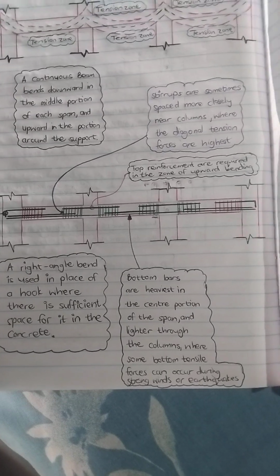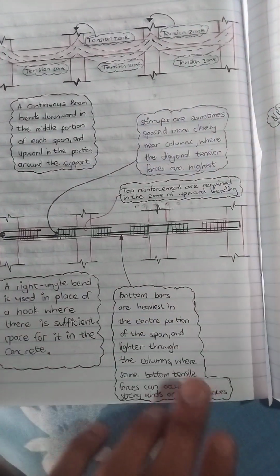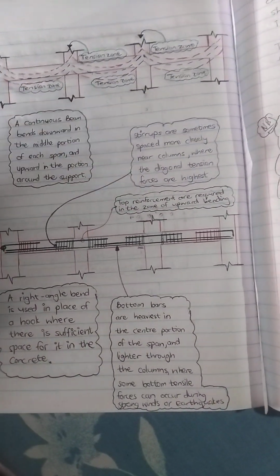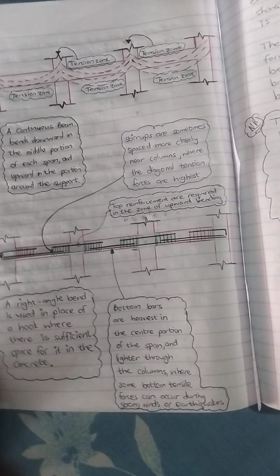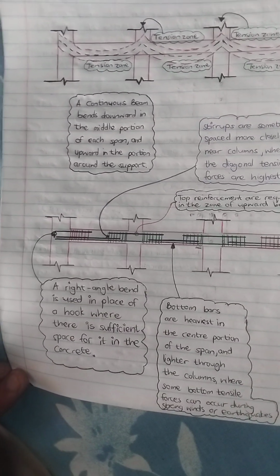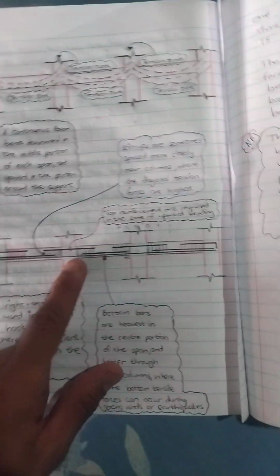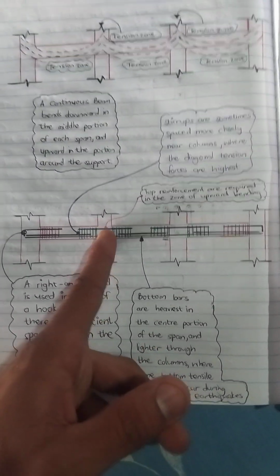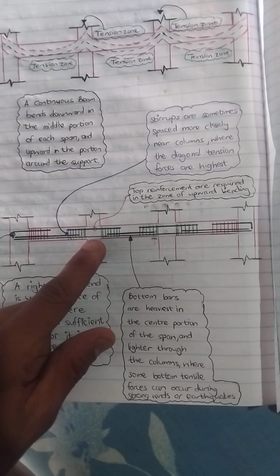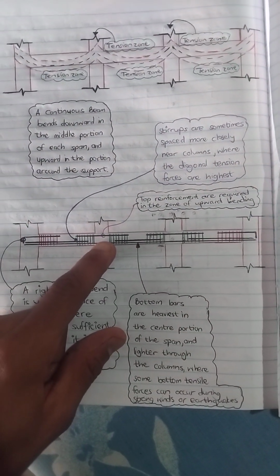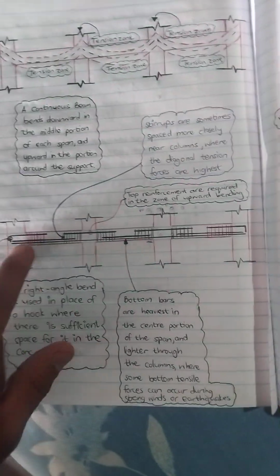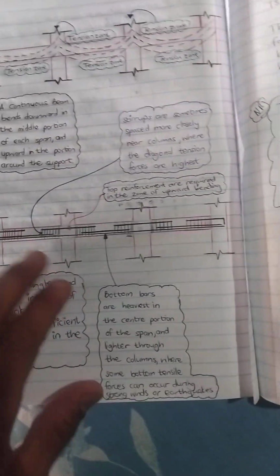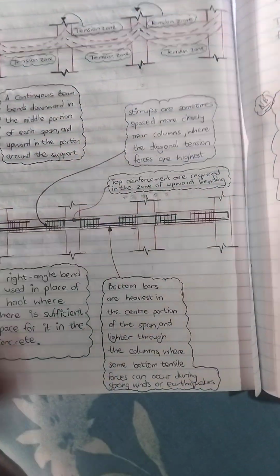And I think I mentioned somewhere, I'm just gonna read, I think I mentioned somewhere the reason why we put one bar straight through is in cases of when we have heavy wind loads and when there's earthquakes, then usually you get some type of tension in the bottom section of your column, where your column runs through your beam. But that's why you have to put one steel piece straight through.